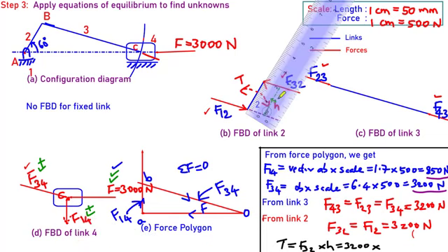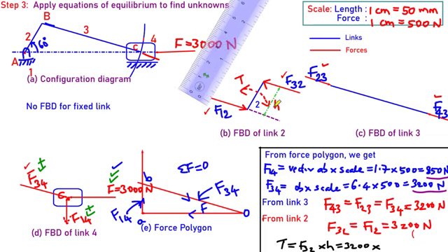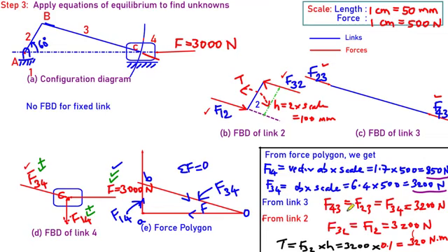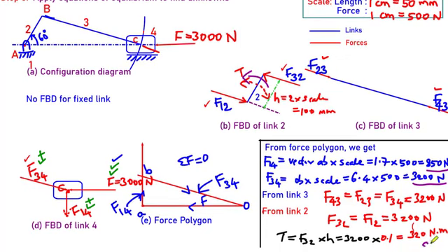It comes around 2 centimeter for me. So 2 multiplied by scale comes around 100 mm, so I will get 0.1. So the answer will be 320 Newton meter. Can we identify the direction? When these two forces act as a couple, the couple will be acting in this direction, which we call the counterclockwise direction.